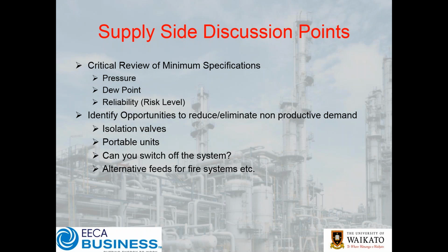So you're obviously from a plant that's looking to make pharmaceutical grade products. So your requirement is what, sort of minus 30, minus 40 degree dew point? The standard recommendation is minus 40, absolute maximum minus 20. Okay, so are you trying to control to minus 40 or control to minus 20?